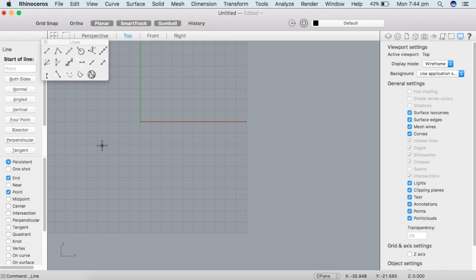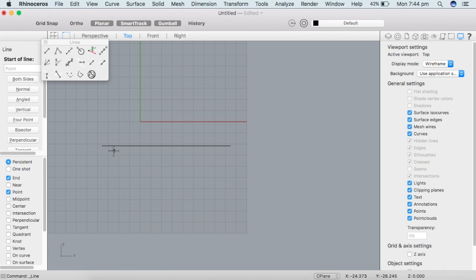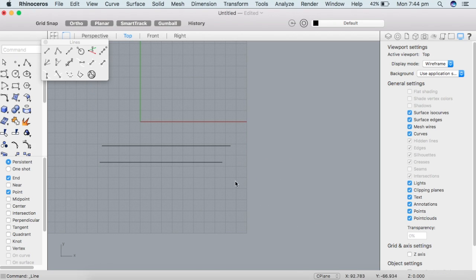The first is line segment. It's basically a 2-point line. To make a straight line, just keep on pressing the shift. It'll make a straight line, or you can turn on the ortho mode and then do that. To turn the modes on and off, in the Mac you can obviously see them right here, and in the Windows it's down here or somewhere, right?